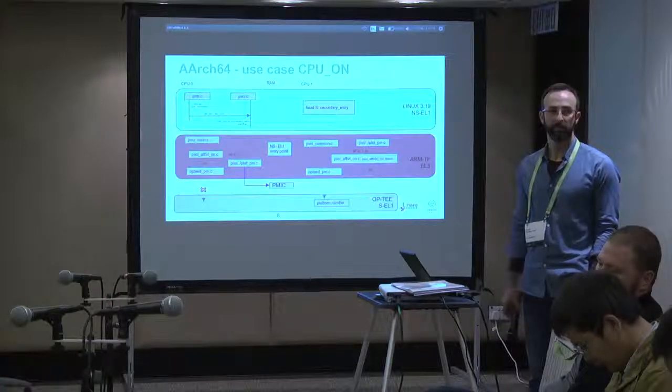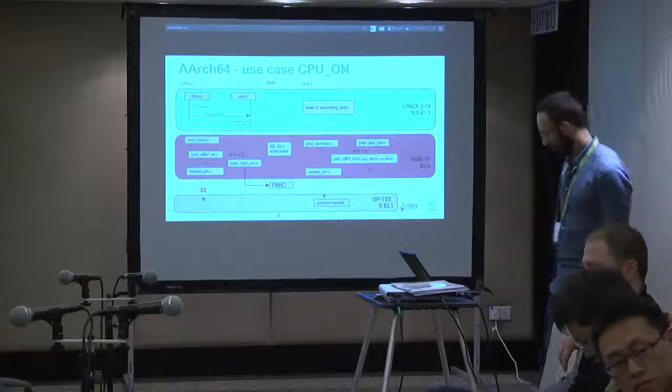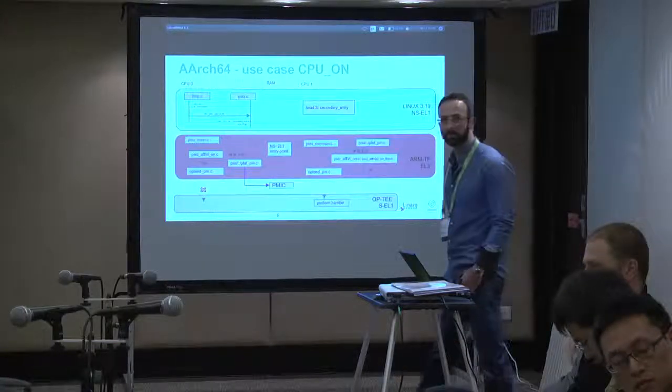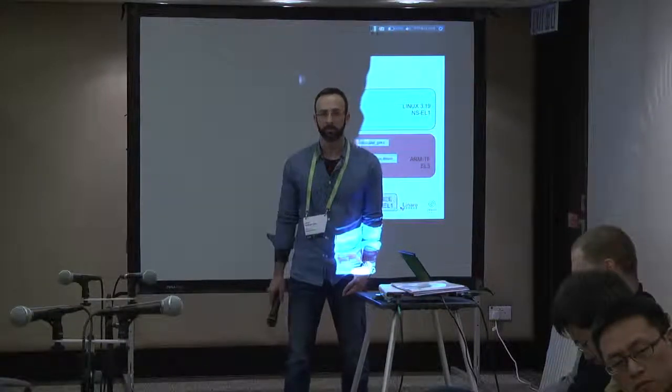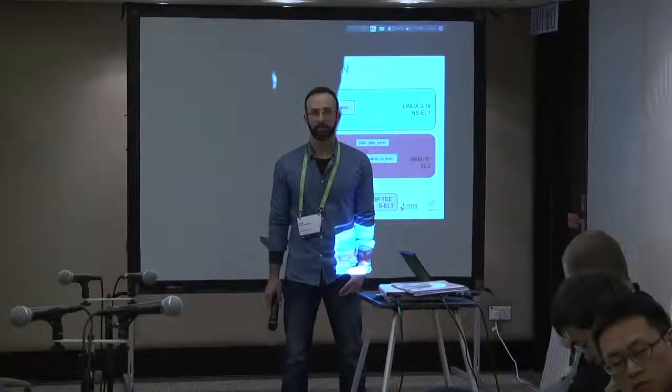But I suppose that if your PMIC is on the I2C bus, which is shared with other peripherals used by Linux, at this point there is no trust anymore, because Linux can power down the system anyway without asking the trusted firmware to do it.